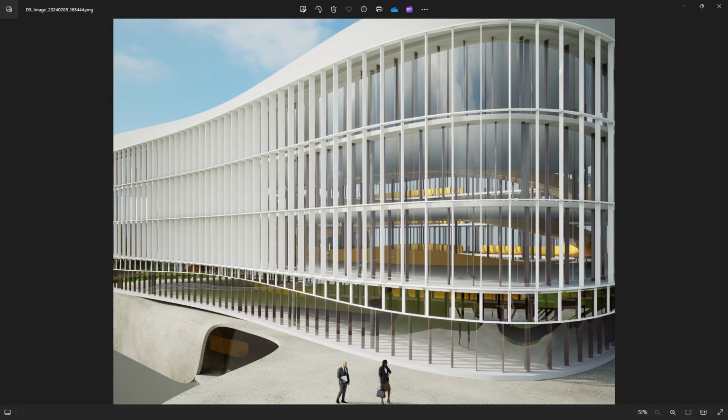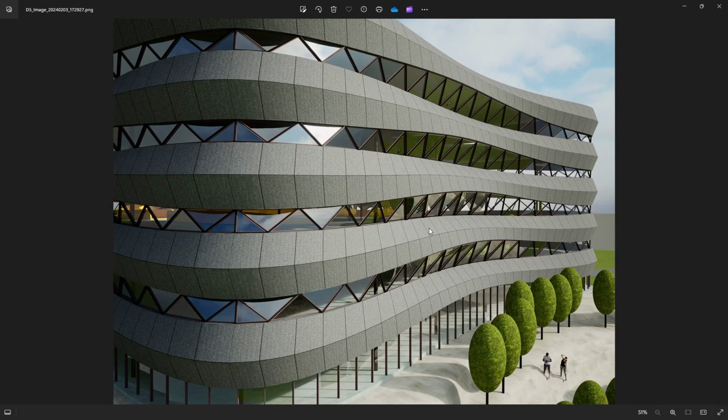The next one was a bit more forced in a way. Just something that's been done quite a bit before, just trying to see whether it's achievable with Grasshopper. And the one feature that I do want to point out here is the fact that the glazing is triangulated, which means that each panel is planar. So you could send this to a CNC machine or fabricator, and using Grasshopper, or any other computational design program, you can actually give locations for each one of these, whether it's on the first floor, second floor, all the way up to the top.